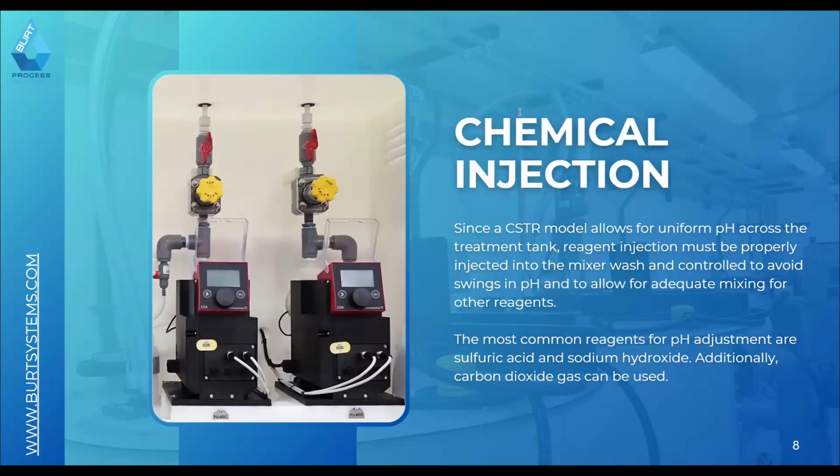And your reagent chemicals are considerably stronger than your waste stream. So you're talking about usually using things like sulfuric acid or sodium hydroxide. There are a few other ones that can be used, which obviously can be talked about for varying situations. Those are the two most common. And the reason that they're utilized is, one, cost. Sulfuric acid and sodium hydroxide are relatively inexpensive. Two, they have very low vapor pressure. So you don't have to vent them through a scrubber system or vent them as part of the injection process, since they're not going to be off-gassing when doing pH neutralization reactions.